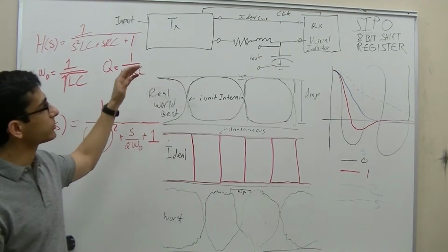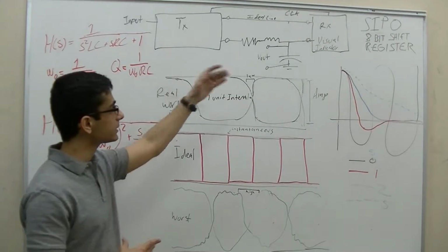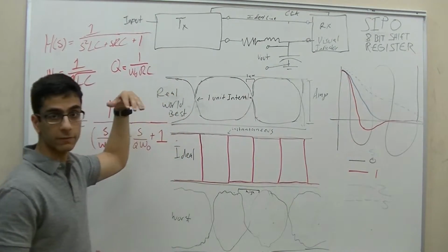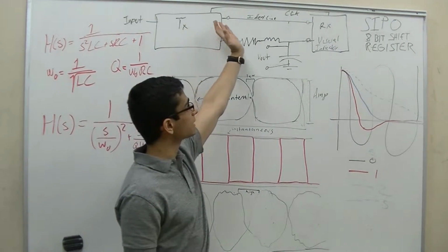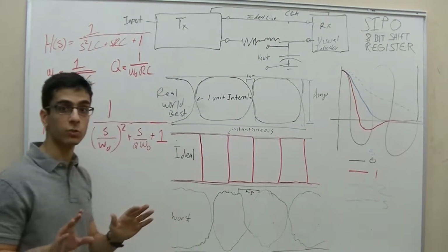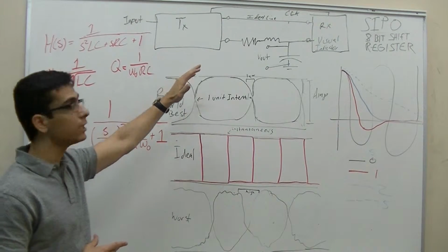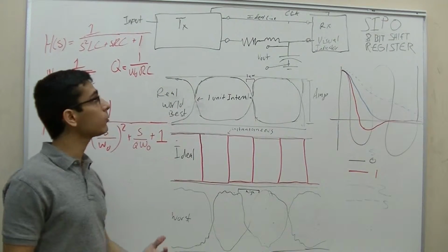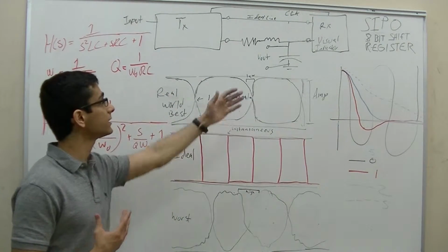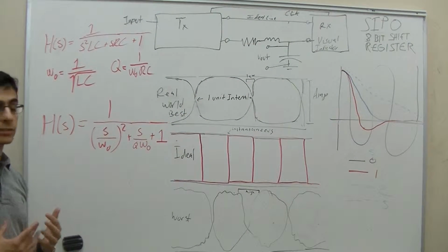So the idea of our lab was to have a transmitter and a receiver working in conjunction to transmit to the receiver a data input that we define to begin with, and ideally it will go across an ideal line and have no distortion in the signal because there's no impedances, no components in the ideal line, and we will get out what we get in. In a non-ideal line and in the real world, you'll have varying impedances due to capacitors and inductors working together that will distort the signal.